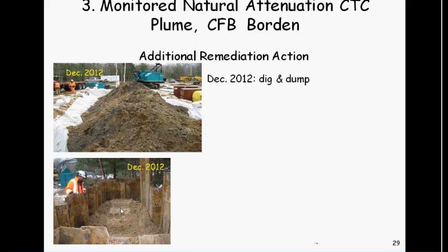So you end up with 100 little subsamples, but the scatter is from 0 to 10% coal tar creosote, and it's so scattered, the average has very little significance. And that's surprising because we mixed the coal tar creosote with a uniform sand. We emplaced it as uniform sand. And the coal tar moved around enough to get very inhomogeneous in uniform sand.